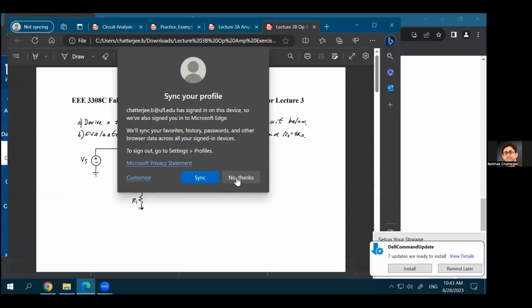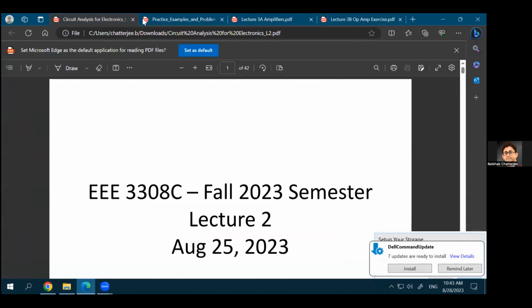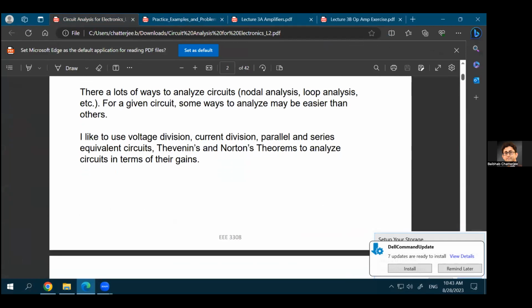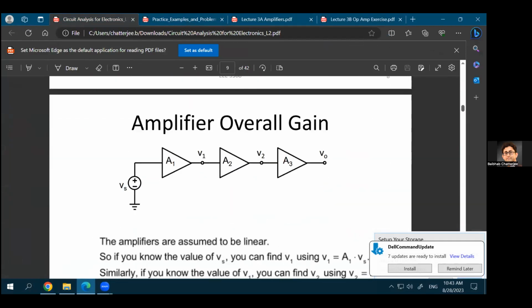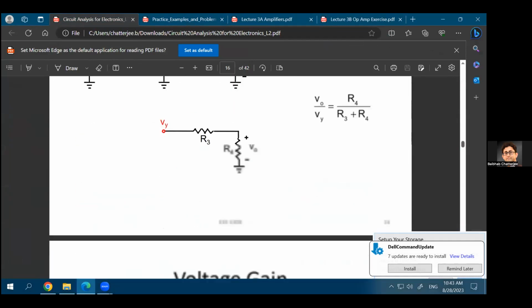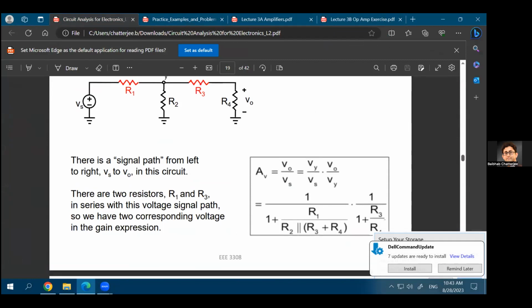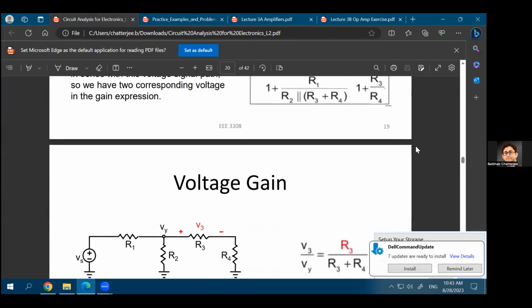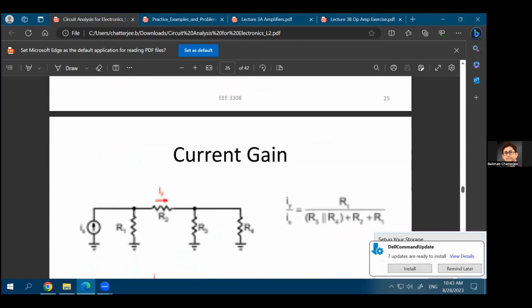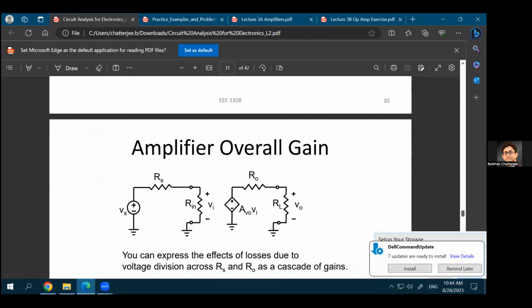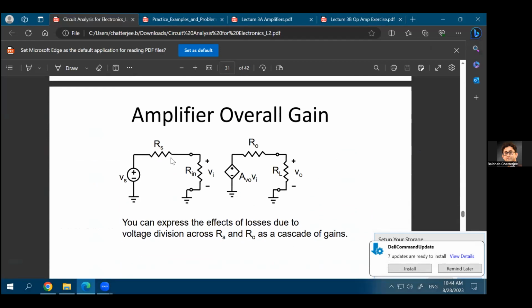All right, coming back to what we were discussing last week. In Friday's lecture, we looked into Ohm's law, voltage and current division, amplifiers, and a few examples of how to solve for voltage gain or attenuation in this case, because this is just a passive network. There's no gain element, no amplifier here. Later on, we looked into the equivalent circuit diagram of an amplifier, which was this. And we looked into what role the source resistance, the input impedance of the amplifier, the output impedance of the amplifier, and the load resistance play in the overall gain of the circuit.